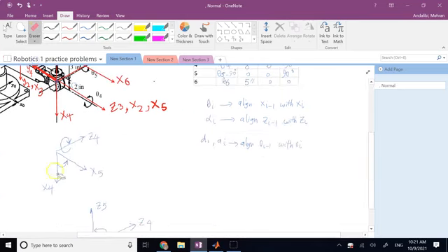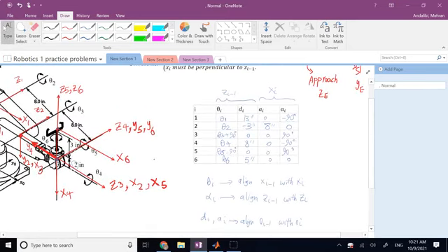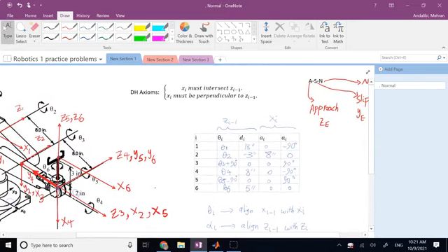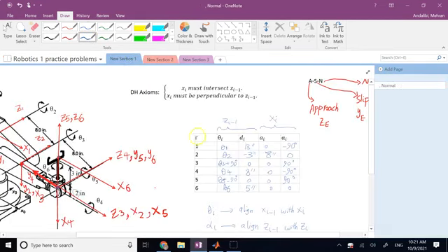And now I'm ready to apply them to the general homogeneous transformation matrix of DH, which, if you remember, it is of this form. So you take the values of each row, the thetas, d's, a's, and alphas of each row, you apply it, it gives you one A matrix. Each A matrix will take you from one frame to the next. So if you apply row 1, these 4 numbers, it will take you from what? Frame 0 to frame 1.